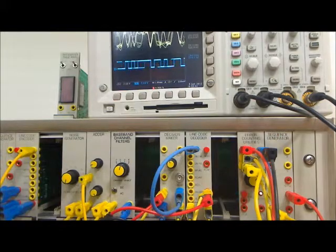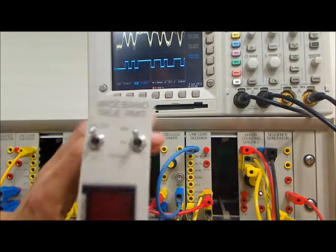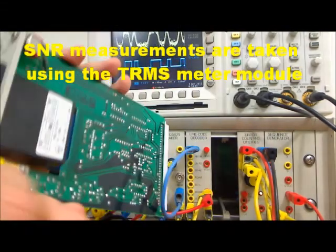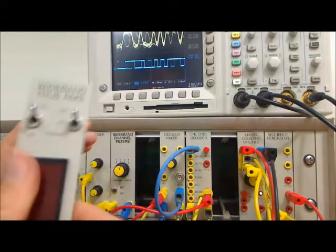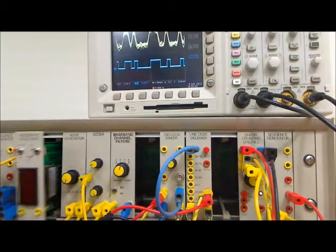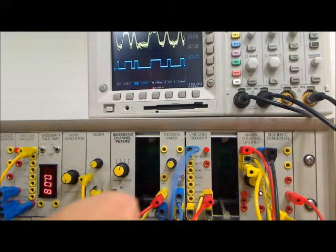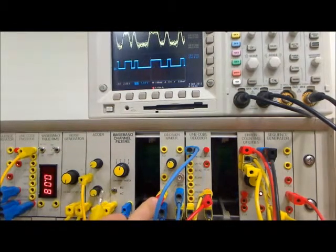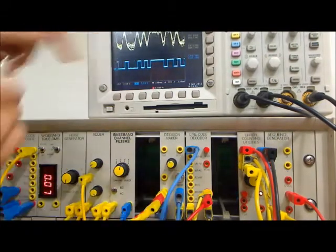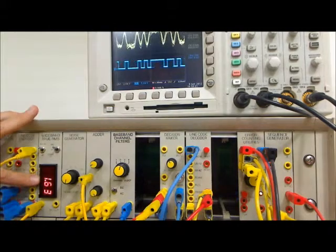Now, one thing we haven't looked at at this point is how we actually measure signal to noise levels. That's simple enough. We take this module, a wideband true RMS meter, which has an 8-digit true RMS meter and a 3.5-digit display. It's actually a very accurate module. Plug it in, take a lead. Let's take a look at the signal at the decision maker, which is up here on screen. Take the lead, input the signal into the true RMS meter. So now you can see a reading.